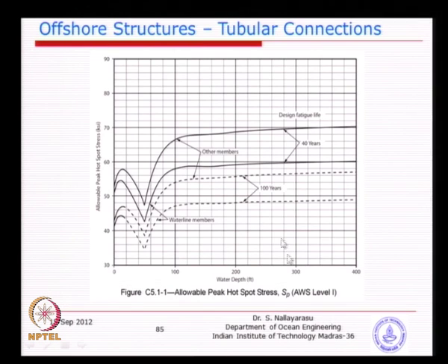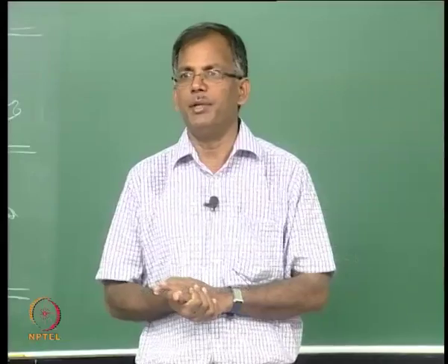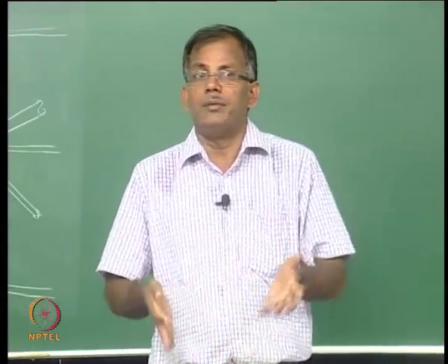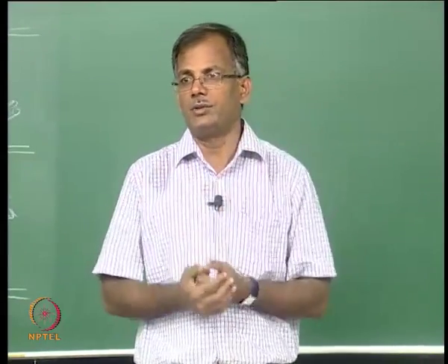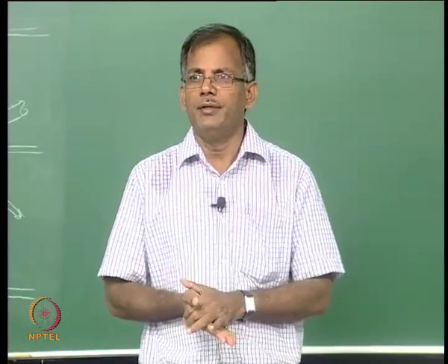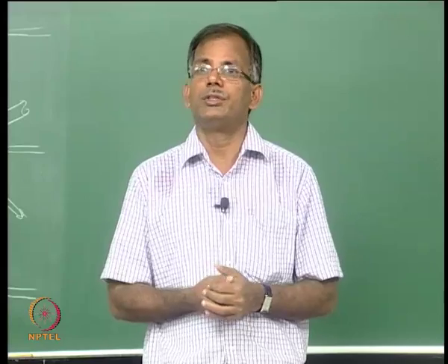You can see here is basically the water depth, and your allowable stress is straight away coming from this type of graph. It is not recommended to use this method for detailed design, basically meaning for implementation purposes, but this can be used for screening purposes. For example, when you start to look at a jacket or a structure in the very initial stage, you do not have enough time, maybe you could use this as just a starting point.